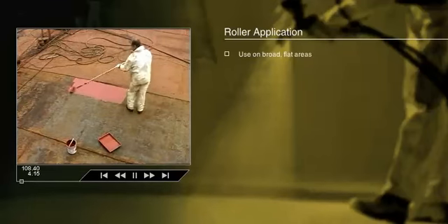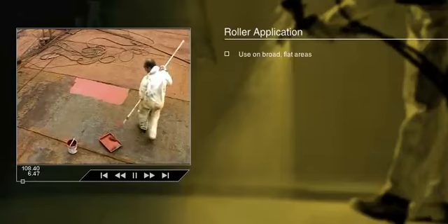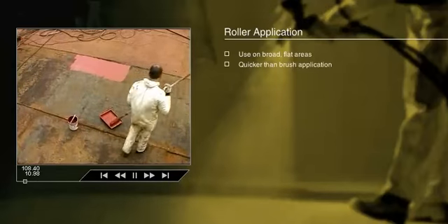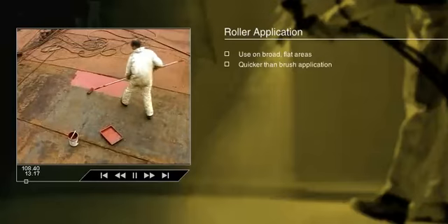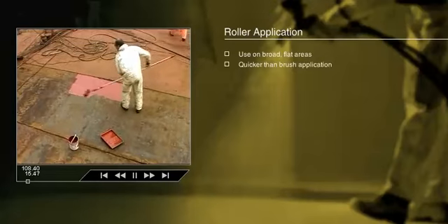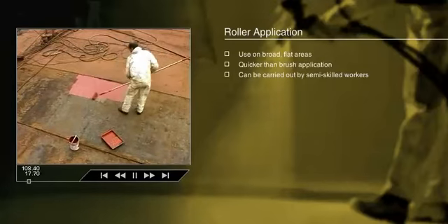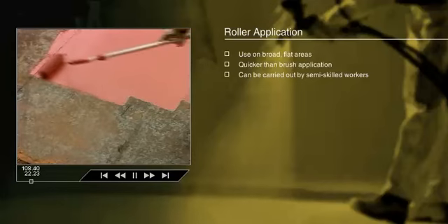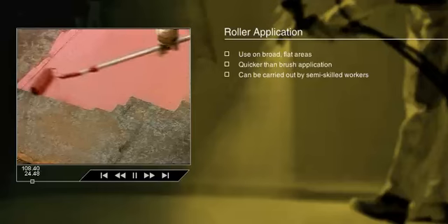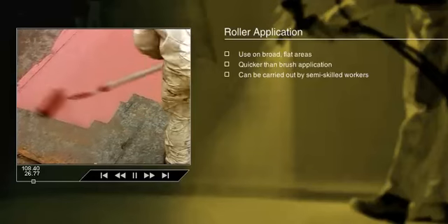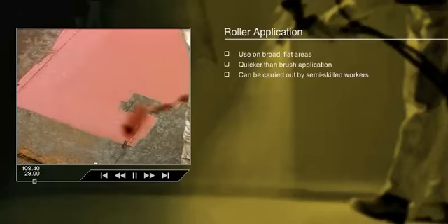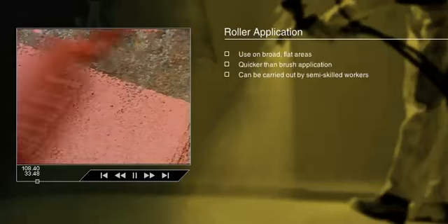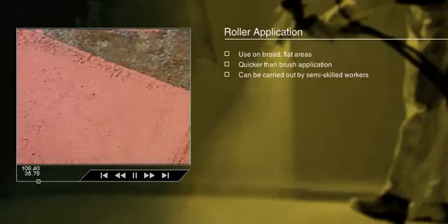Roller application is of particular value on broad, flat areas. Although not so quick as spraying, it is usually quicker than brush application. Another advantage is that it enables the semi-skilled painter to obtain a reasonable and consistent standard of finish. There are no particular difficulties in roller application, and the technique is soon acquired.